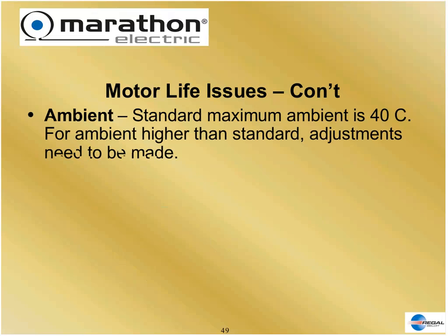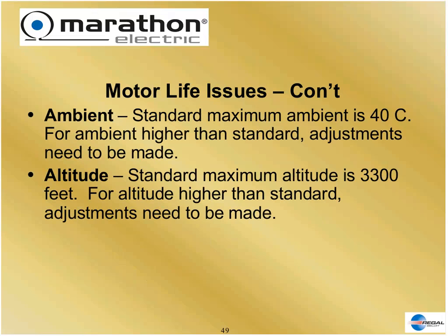So, the standard ambient is 40 degrees centigrade. For higher ambients, we have to make an adjustment. You'll see what the adjustment is in a second. 40 degrees centigrade is 104 degrees Fahrenheit. It was derived because that's the temperature that the specification writers determined would be the hottest temperature that human beings would like to work in. The standard for altitude is 3,300 feet or 1,000 meters.